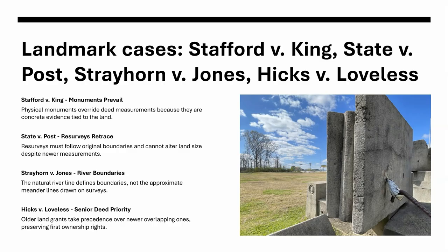Monuments prevail. The reasoning was simple but profound. Numbers can be wrong. Chains can stretch. Compasses can err. Transcriptions can mistake distances. But monuments, trees, rivers, iron rods, stone mounds, are physical evidence. They were set or called for by the original surveyor, and they tie the record to the land itself. It is a reflection of intent. From this case, the court gave us the hierarchy of dignity of calls, which still governs today.